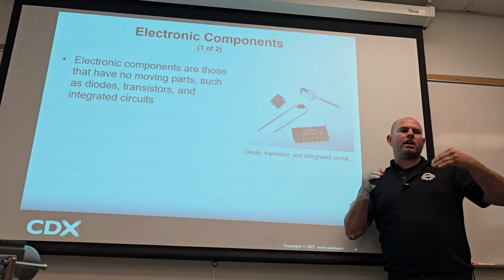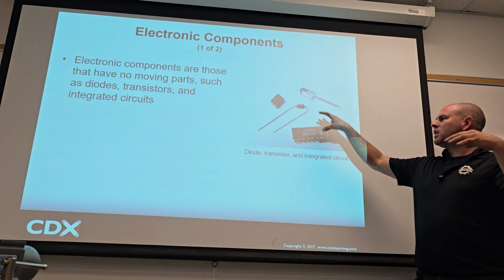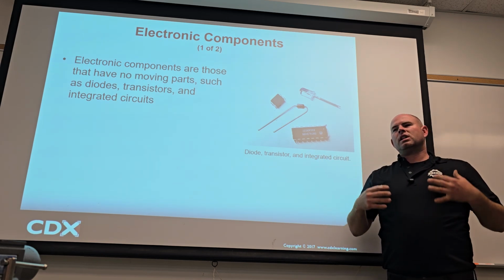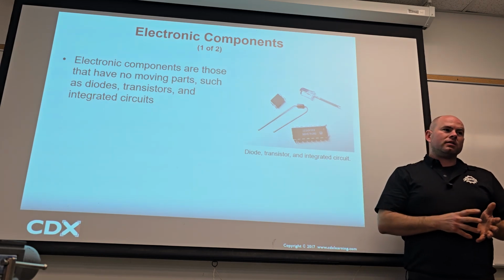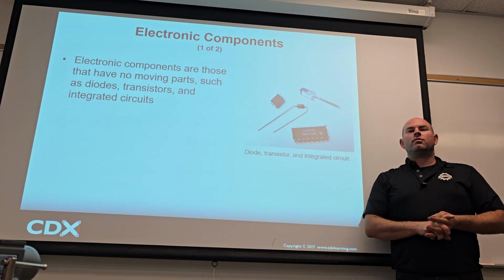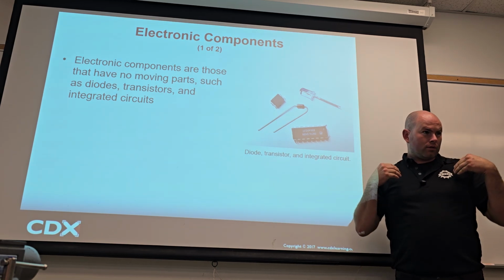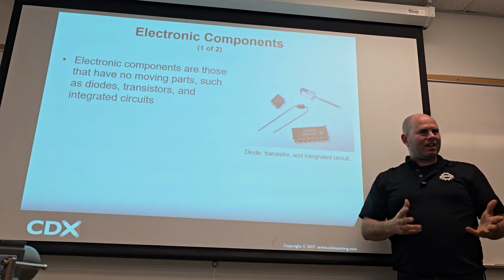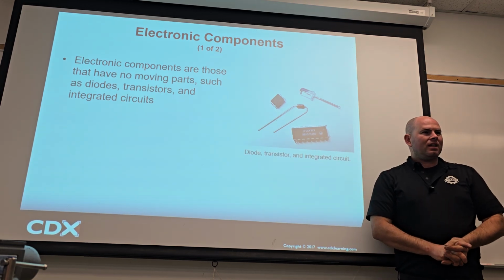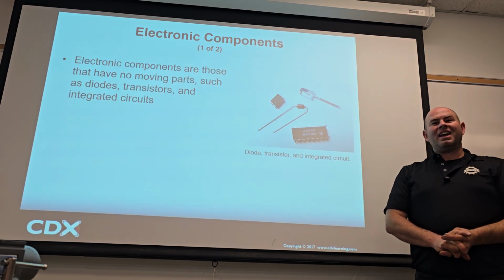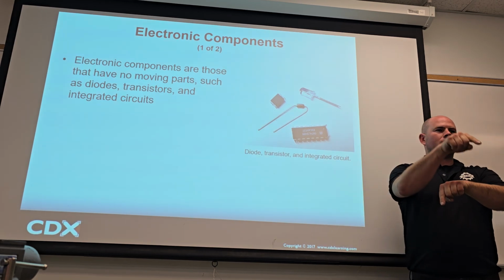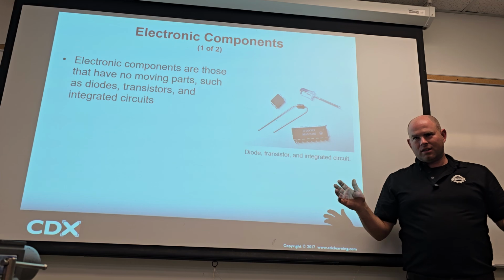We wouldn't say, oh, we're going to go in and desolder the processor and resolder a processor. It's just not what we do. Now, somebody does, but that's not what we do. What we do is we tell them it's the computer, it's the wires, or it's the sensor. Does that sound too easy? It's not really that easy. And if you can accurately diagnose if it's the sensor, the wires, or the computer, you're doing great.